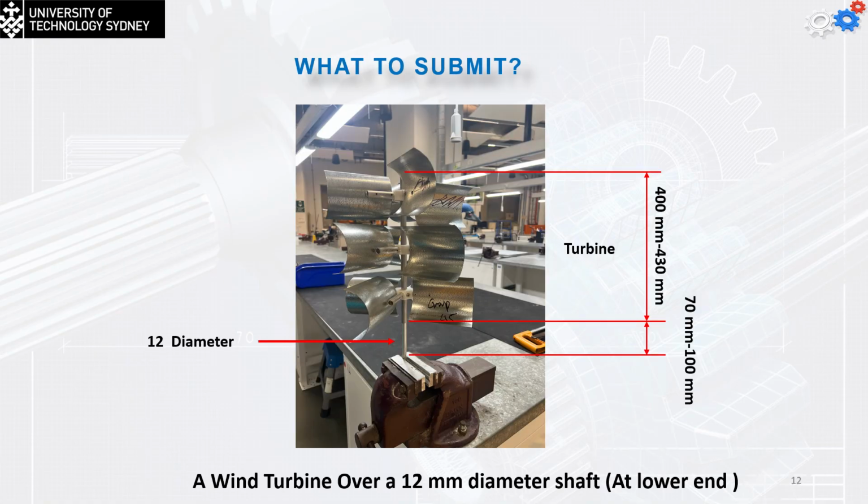So what to submit? What we need you to submit is going to be the shaft and the turbine attached to it. Once again, the turbine section is going to be anything between 400 to 430 millimeters, while the shaft end length is going to be anything between 70 to 100 millimeters. The diameter at the end should be 12 millimeter diameter. Okay, so the wind turbine over a 12 millimeter diameter shaft at the lower end.